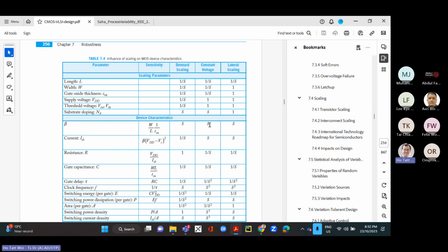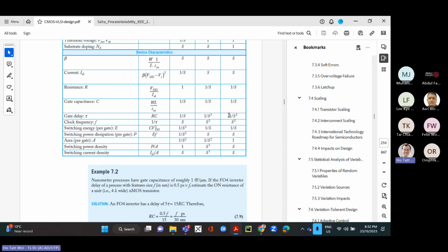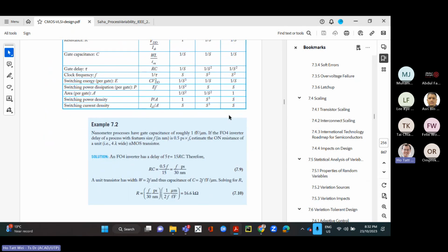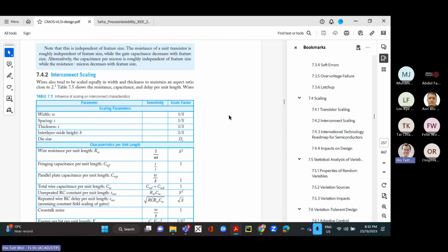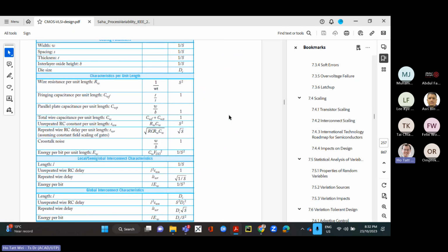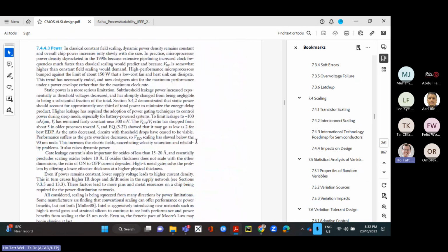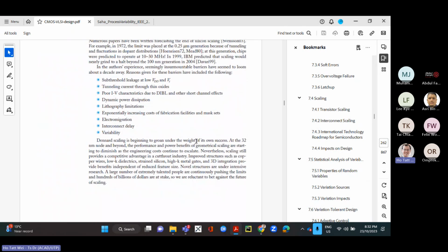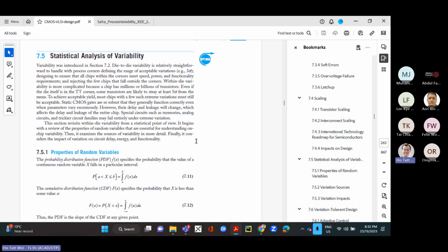That's called Moore scaling. But nowadays, that scaling law is a little bit broken already because we are so small. There's still improvement, but you hardly see too much improvement in speed. It's more of density, and maybe a little bit of power, but not too much. The scaling part is no longer true because we are down to like 3 nanometer devices. So you're just getting density, but you're not getting the benefits of power reduction and speed increase anymore. But you'll still be able to squeeze more devices.